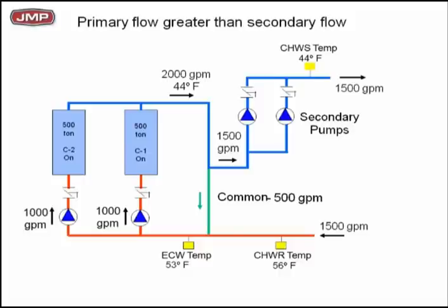So each chiller now has 53 degree return water, 44 supply, 2 chillers running. Everybody's still happy. Everybody's working fine. And this is a mode the chiller's running all the time, the primary, secondary. So each chiller is 75% loaded. There's a 9 degree delta T, 53 return, 44 supply, 9 degree delta T, and the design was 12. So I'm 9/12. So each chiller is 3/4 loaded. Typical operating condition in the system.